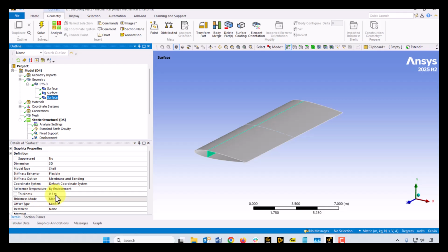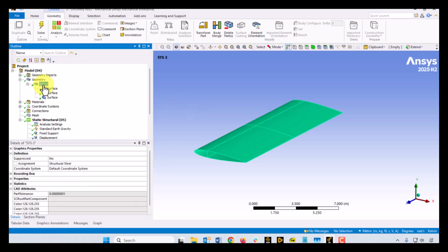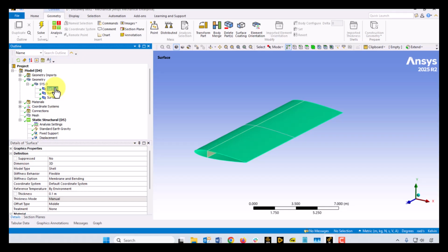have to give it a thickness. Each of these a thickness, and that's a design variable. I just gave it a fairly substantial thickness, which we can visualize in the mesh, just because otherwise I was getting large deformation. This model doesn't have enough spars or ribs to use low thickness. So that's something you want to play around with.